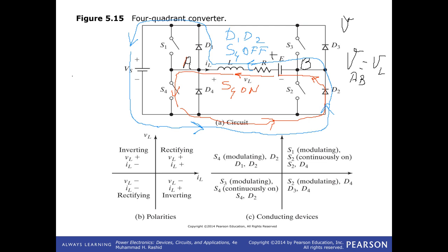But if you put it off, say S4, then you are going to send some of the energy back to your system. It's a kind of step-up action, by the way, since this voltage actually is lower than Vs. However, with the support of the voltage here, the current is going to continue and connect it to the higher voltage value. Step-up action occurs.